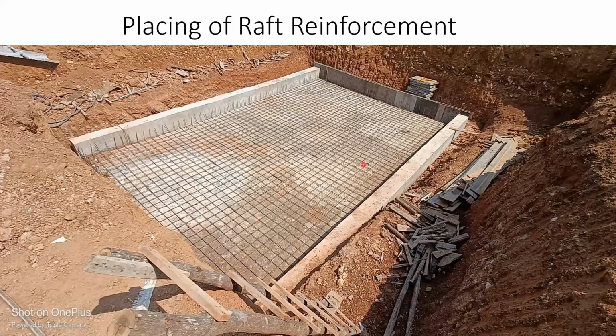When I say raft foundation, we'll be putting a bottom mesh. So this is my bottom mesh. Then we'll be keeping a chair here. I'll draw a chair. We'll be keeping a kind of chair here, and over that I'm going to keep my top mat. Since it's a raft foundation, we'll have a bottom mat and also a top mat. Again, the bars will first be placed in the shorter direction. This is my shorter direction, and then the longer direction.